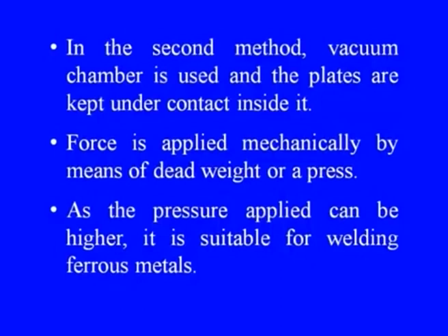In the second method, a vacuum chamber is used and plates are kept in contact inside it. Force is applied mechanically by means of dead weight or a press. As the pressure applied can be higher, it is suitable for welding ferrous metals.